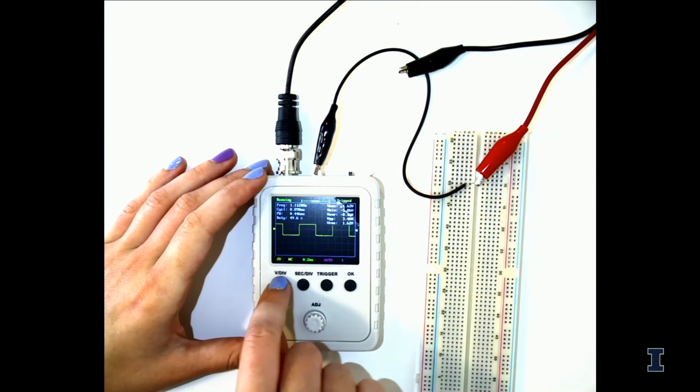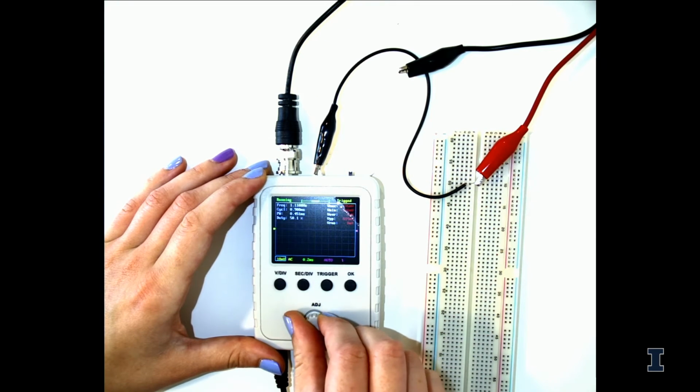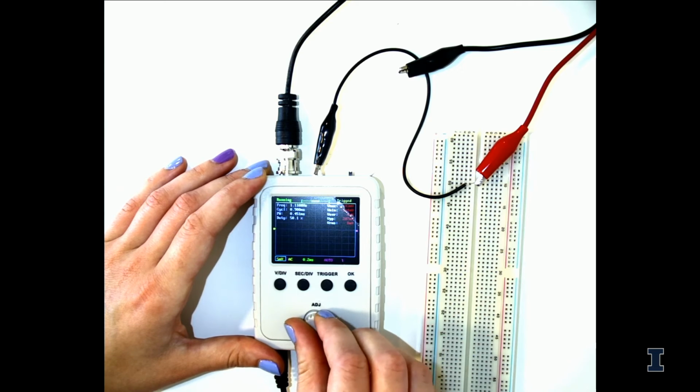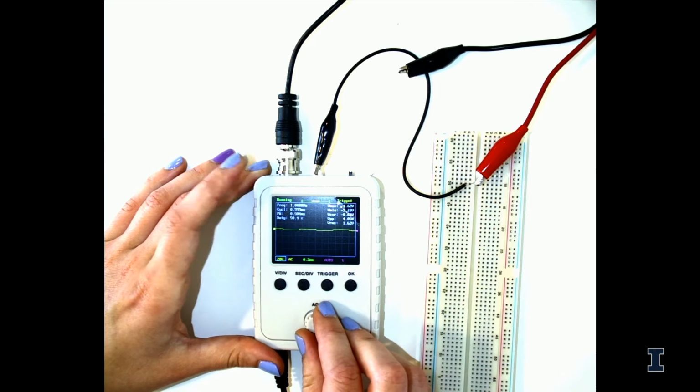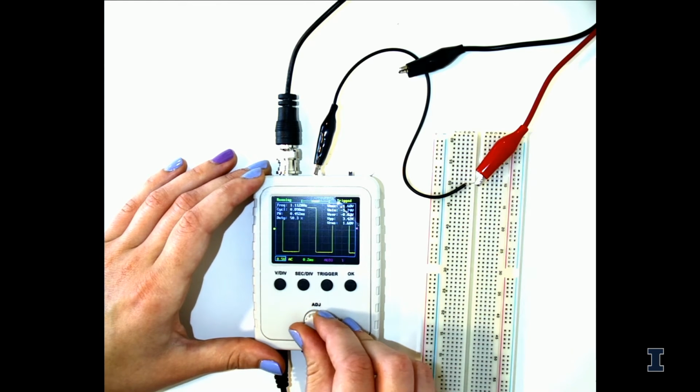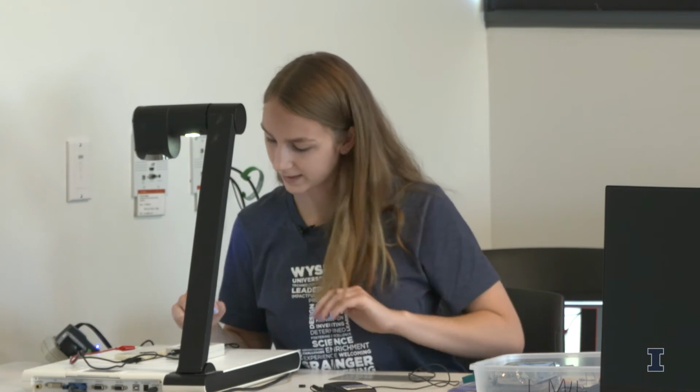So the range for the oscilloscope, let's just see here. It looks like you can go down to 5 millivolts as your lowest, and up to 20 volts as your highest. So you've got a pretty good range. And that's per division, right? So with 8 divisions. Oh, times 10. 4 divisions vertically, so you can measure up to 80 volts. Probably not safe, but. Yeah, so for basic purposes in the projects you'll be doing in class, you won't be going over that. And if you have under whatever the minimum was, you're basically at 0 volts at that point, and you won't be able to power anything.